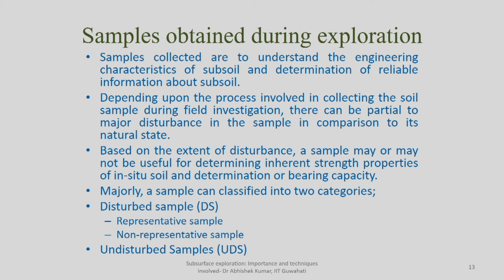Okay, now so far we were discussing different kinds of methods by which you can advance your boring exercise, depending upon whether you are talking about soil, where you can push the auger into the soil and collect the soil sample. On the other hand, as you go deeper and deeper, because of overburden and confining pressure, it may not be applicable. Similarly, if the water table is shallow, it may not be possible to collect the soil sample by auger boring from soil below the groundwater table. So, you go for wash boring.